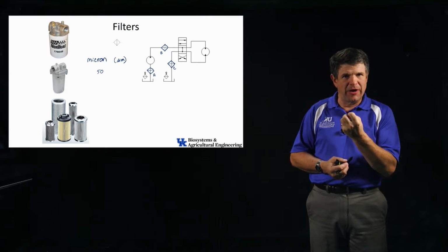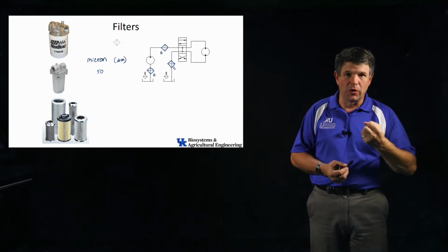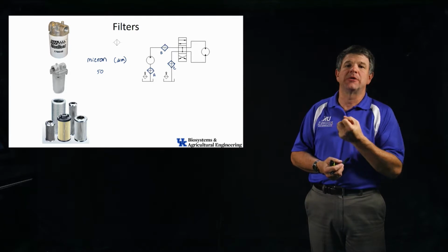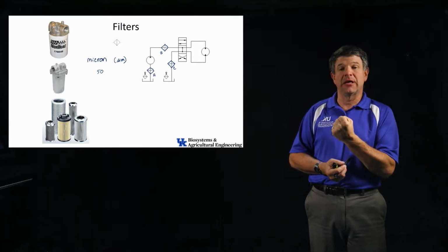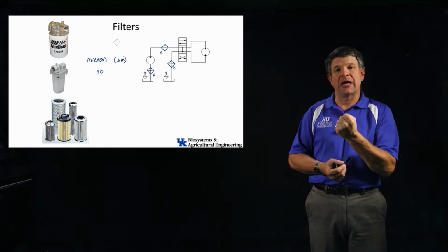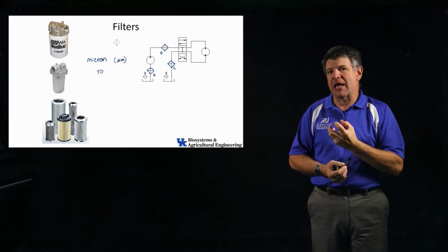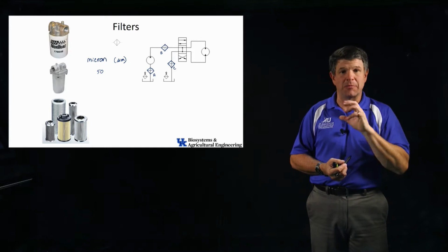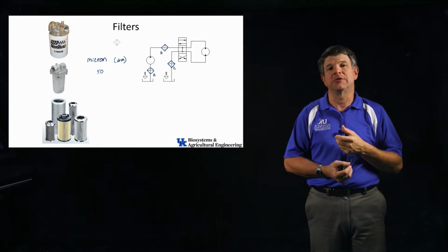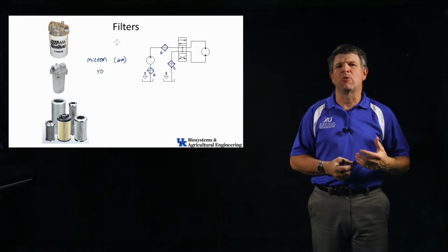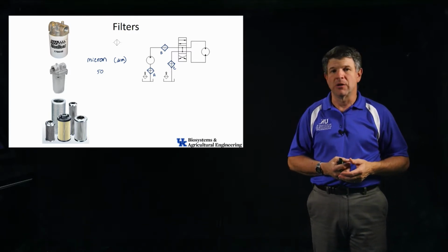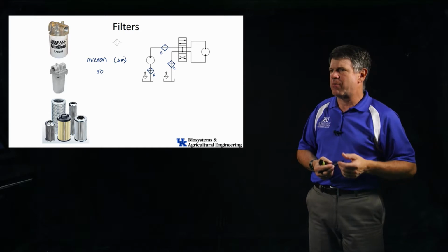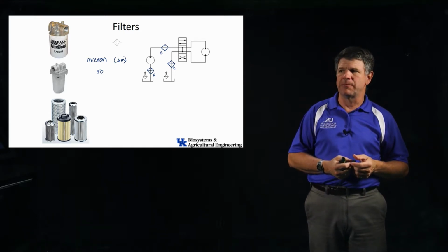And so we get these vapors, and as I mentioned before, if those little bubbles, vapor droplets, go through the pump, they will collapse when they get into the high pressure side of the pump, and that collapsing can actually damage the surface of the pump. It actually pits and corrodes the pump. It's very noisy, it squeals when it does it, and it can be very damaging to the pump. So you don't let that happen very long. So that's a bad part about putting it at position A. All right, so let's move around.